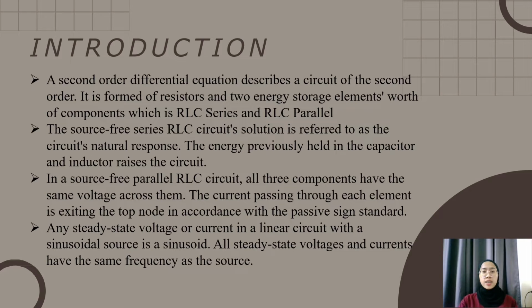Introduction. A second-order differential equation describes a circuit of the second order. It is formed of a resistor and two energy storage elements, which are the RLC series and RLC parallel. The source-free series RLC circuit solution is referred to as the circuit natural response. The energy previously held in the capacitor and inductor excites the circuit.